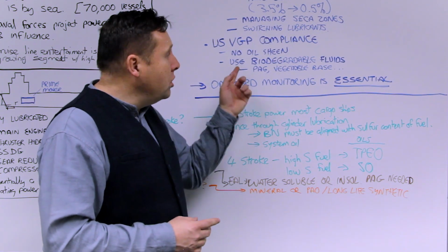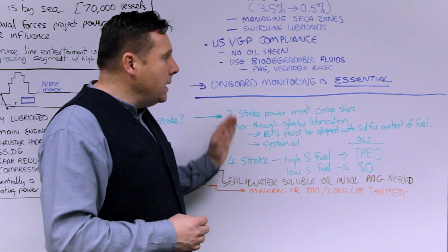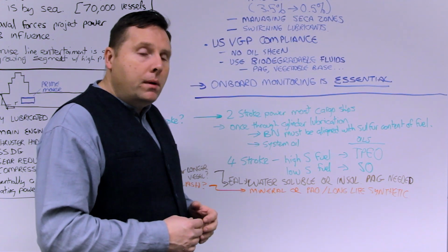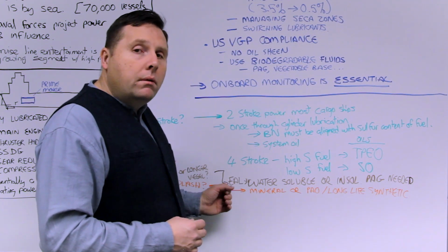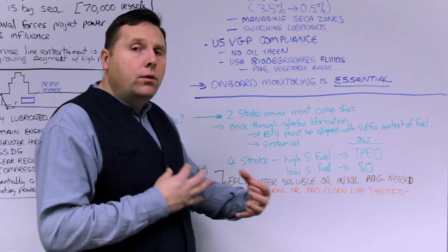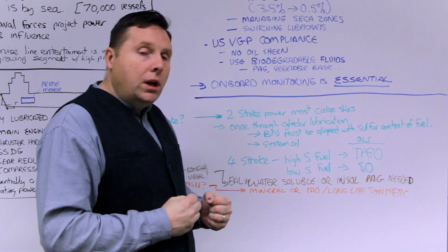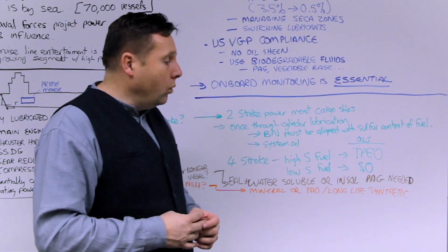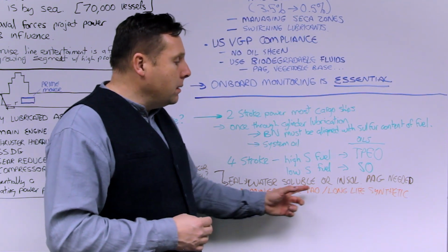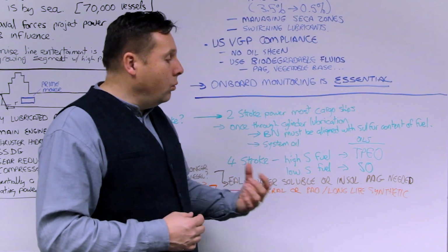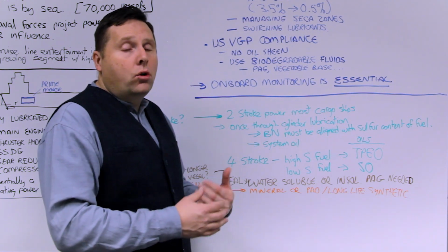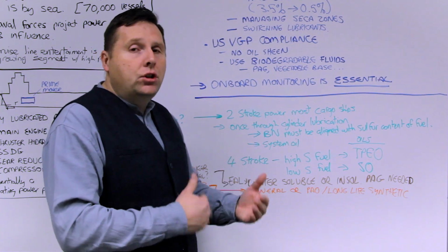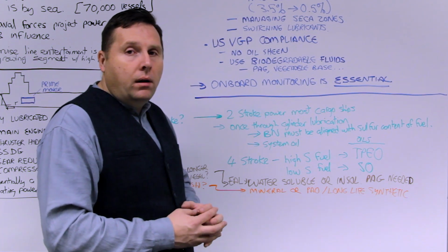In the case of the VGP permit requirements, these EAL, or biodegradable fluids we mentioned earlier, are requiring switch out for many of your rotating equipment, such as your thrusters and hydraulic systems that come in contact with water. And you have to be able to manage these water-insoluble or water-soluble PAGs or EAL-style vegetable oil-based lubricants that are present.